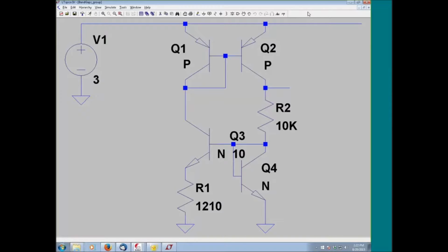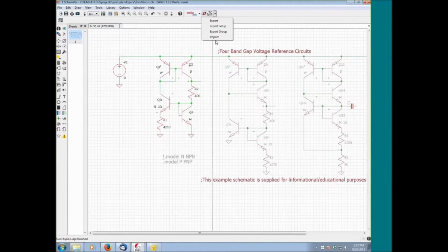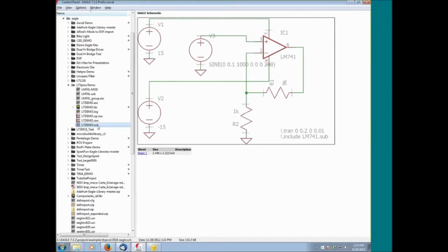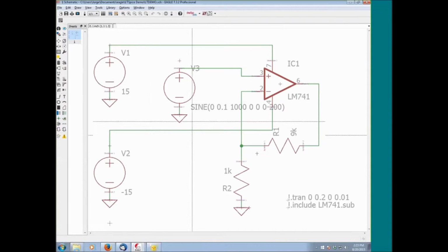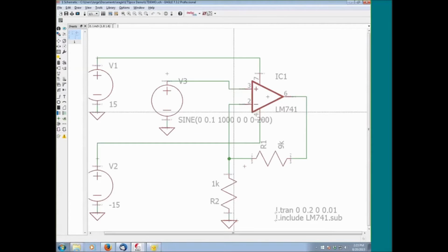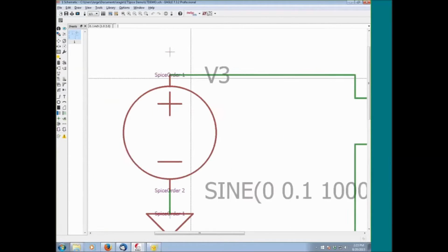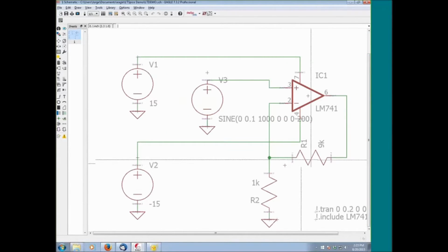So that's the basic functionality of the LTSpice bridge. As you can see, these 4 options here. So let's go ahead and open another design. No, don't save it. That's going to be our demo for today. So open this up. Now, a couple of things I want you to notice. You can see the purple text here. Notice how all of the parts that are going to be simulated have that purple text.